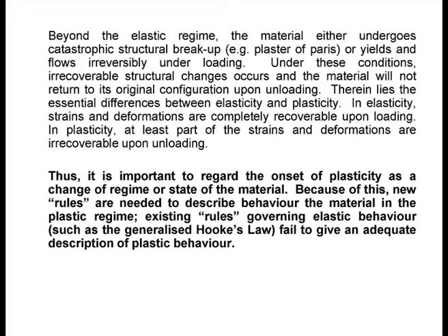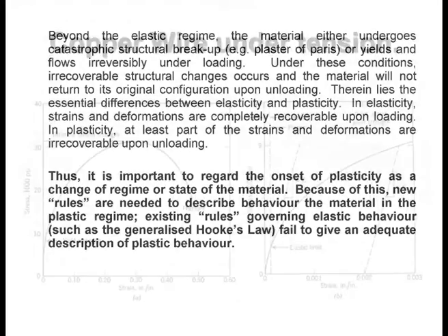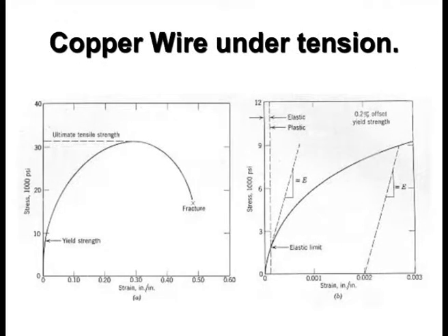The class of material behavior that we are talking about here is a class of material that beyond a certain stress level, if you look at this copper wire for instance, if you load up the copper wire to here and you unload, it pretty much will come back here. But beyond here, say you come up to here, when you unload, it will come down here. It will not come back along here. This is the essence of plasticity.